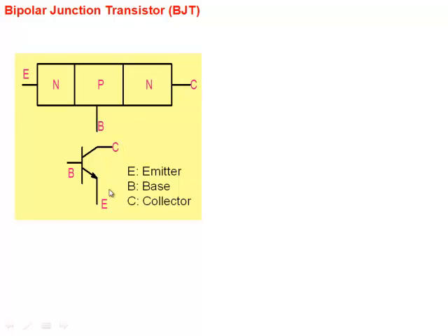All right, so the emitter and collector come from that terminology here. And so the arrow, of course, here that you see, arrow denotes because if the electrons are going from emitter to collector here, then the current, as you can see here, comes out of the emitter terminal here, because the current is opposite to the flow of electrons, so the current is coming out here.